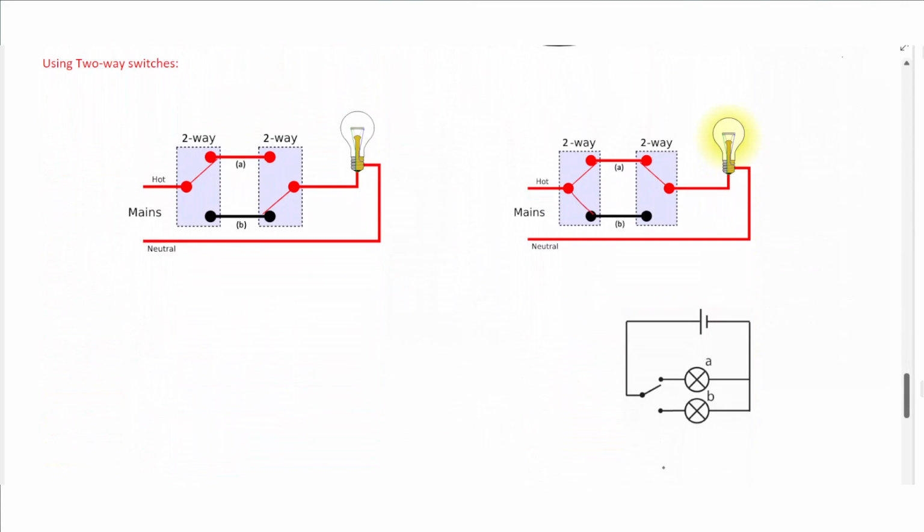Now, for using two-way switches, there are two methods of using the two-way switch. Either using 2 wires and 2 switches, and you can switch on from one of the switches and switch off from the other switch. If you want to switch on, both switches must be connected to the same wire. If you want to switch off, one must be connected down and one must be connected up, or connected to different wires. Or you can use one switch as an alternating switch between two branches.